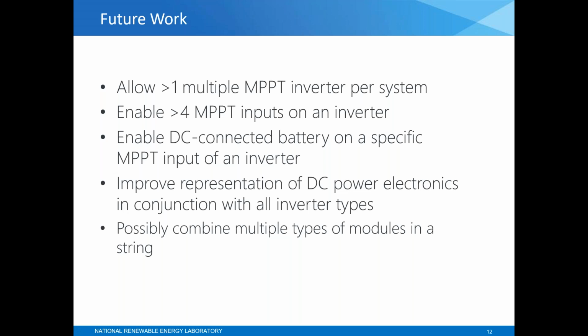The multiple MPPT inverter feature does not actually help model DC power electronics correctly, although there are one or two ways that you could sort of hack the multiple MPPT feature to better represent a system with DC power electronics. But it is on our list to improve the representation of DC power electronics specifically, to be able to be used with all types of inverters, both single and multiple MPPT inverters.